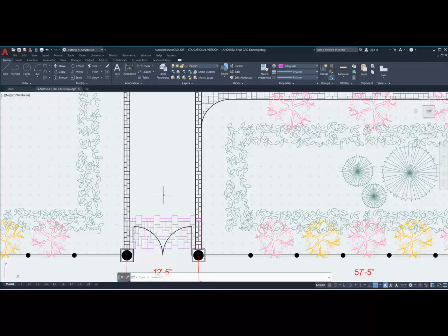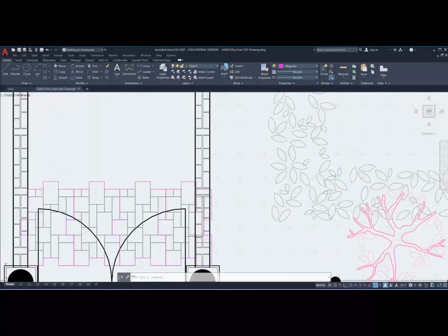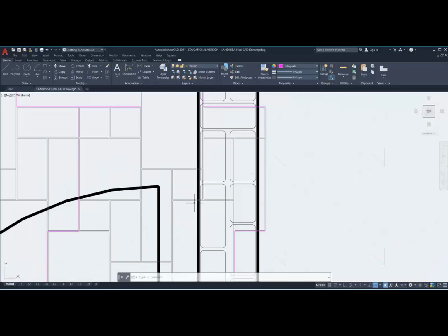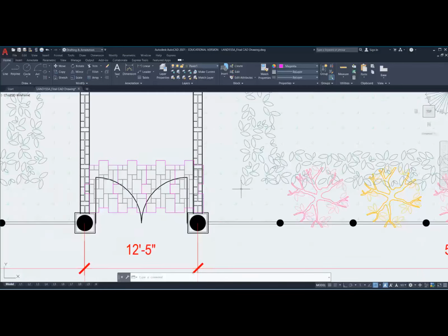A lot of times when I'm actually with the judging panel, we're looking for what we call slivers, where there are none. So if I have a sliver of a tile, let's say that very, very small section, we'll say right away that that project has slivers, which means that project isn't done very well. You've got to measure forwards and backwards. Even though this says 12 foot 5 inch center to center, and that's where you're going to band it, you don't work on that principle.